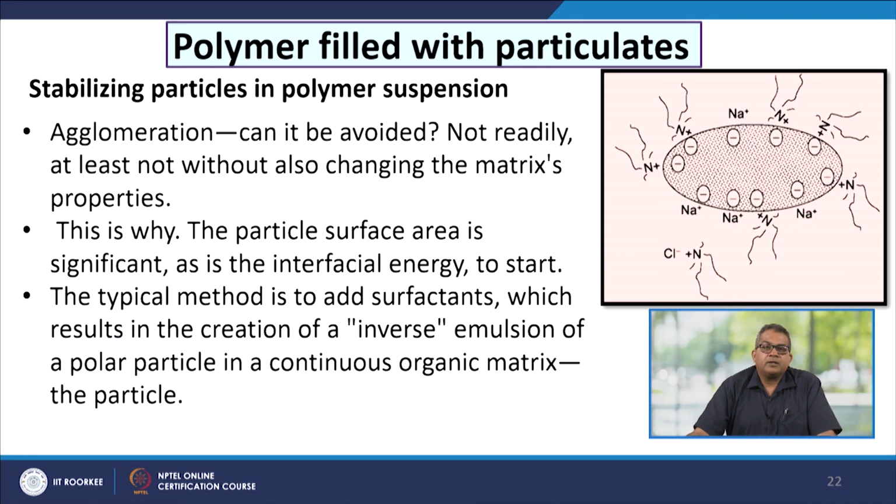Now, can agglomeration be avoided? Not really, at least not without also changing the matrix properties. That is why the particle surface is significant, as are the interfacial energies to start. The typical method is to add a surfactant, which results in the creation of an inverse emulsion of a polar particle in a continuous organic matrix.